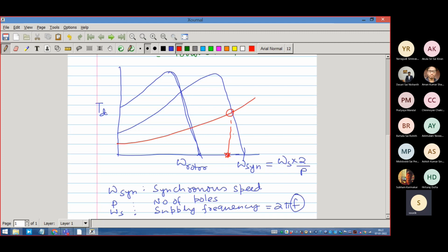But by shifting it, we are able to operate at this operating point, which means that the actual rotor speed has reduced. With the rotor speed reduced, the flow rate has reduced, and we have obtained the pump characteristic we desired in the previous figure. So you see that the power required by the system has reduced. What is the power at this point?